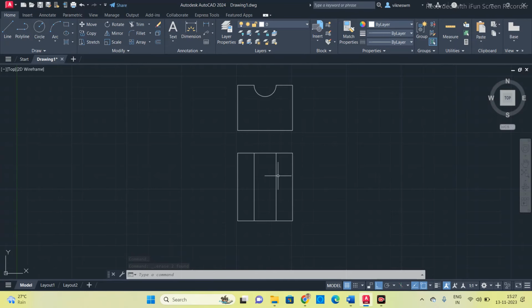So now this is the top view, but we have to put the center line. Since it is a circle, since it is a curved face, we have to mark the center axis. So marking the center axis represents that it is a circular shape. For that I'm going to take another line from the center of this circle, come up to here. From here you draw another line. And delete this line. So we have to change this line to a center line.